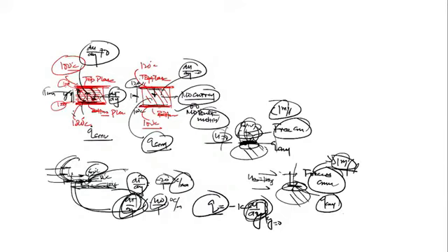The only difference in both cases, either free or forced convection, is that the rate of heat transfer via conduction at the wall is equal to convection in the fluid. Listen, in both cases I should write Q conduction at the wall is equal to Q convection in the rest of the fluid. But what happens in forced convection? In forced convection, Q conduction increases. That's why Q convection also increases.